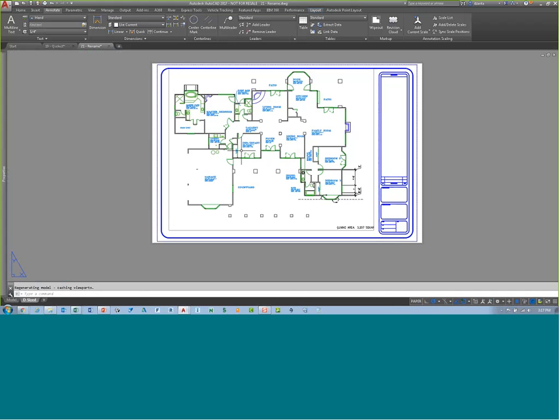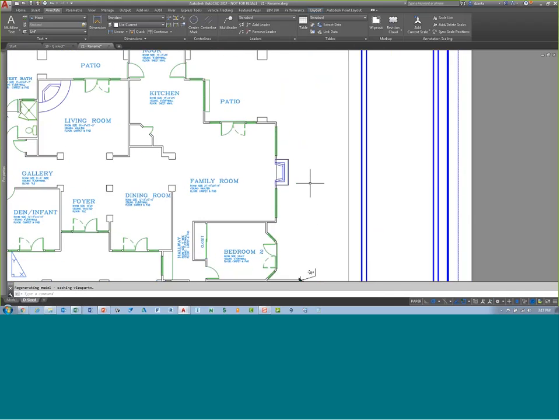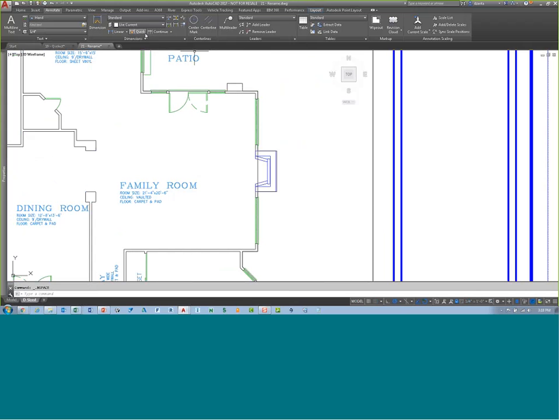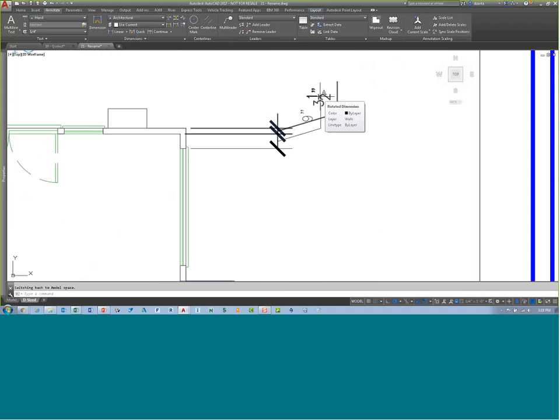Let's go ahead over to the D-size sheet where I have my viewport set up properly and the annotation scale set up properly. Now if I do this off of the architectural annotative style and do the QDim, let's do it for that. We can head over here, click, and it puts it in automatically. So it's a good quick way to do a whole bunch of dimensions. You just have to be methodical about it in the sense of after the fact, clean up what you don't want.